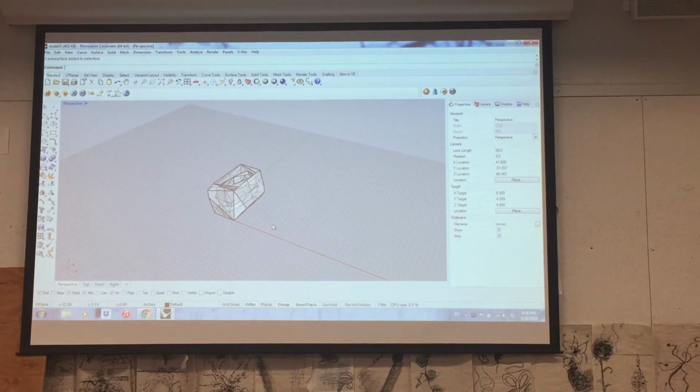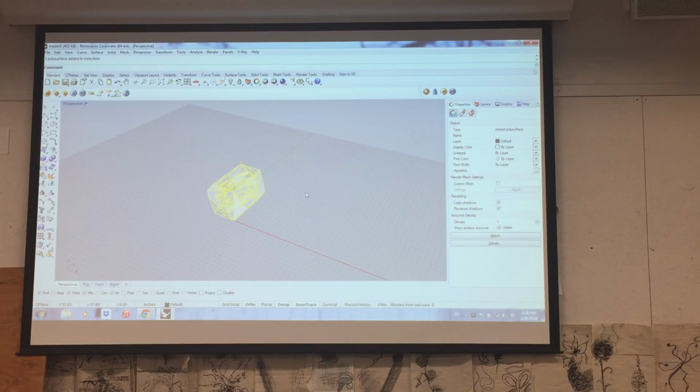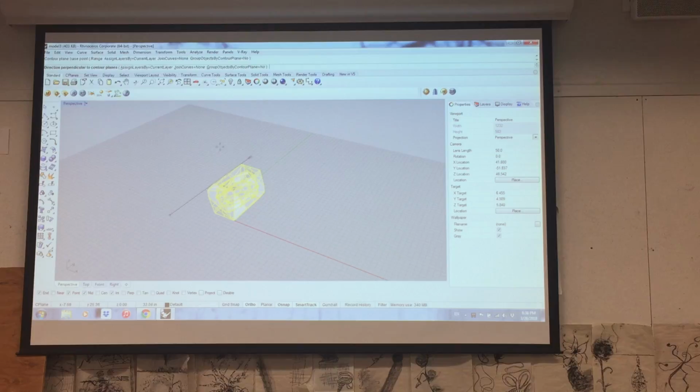So let's say, for example, I want my contours to run this way in the Y. So I'll type in contour. I want it to go this way. And right now it says 2, but my file is in inches, so that would be 2 inches. So I need to change that to, yes, 1/8 of an inch. I'm going to type in 0.125. Same thing. I think I could type 1/8. I've never done it that way.